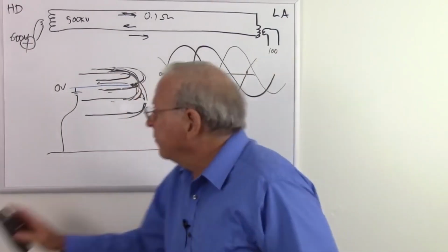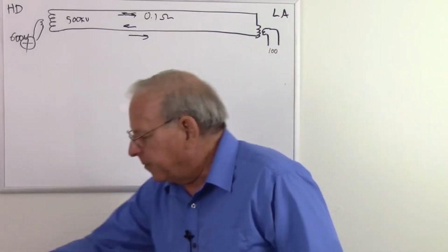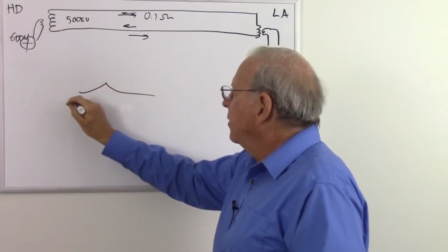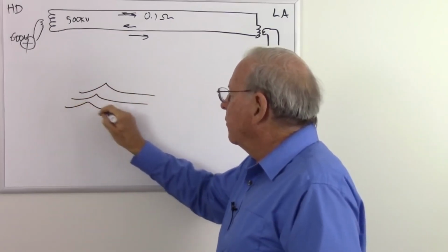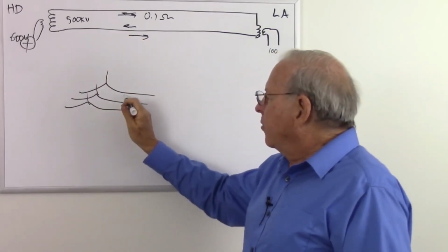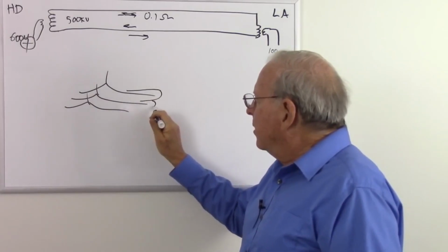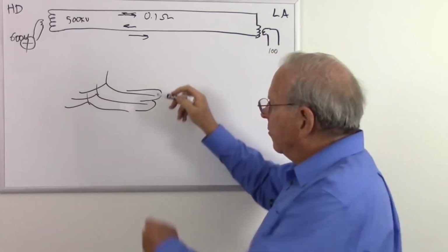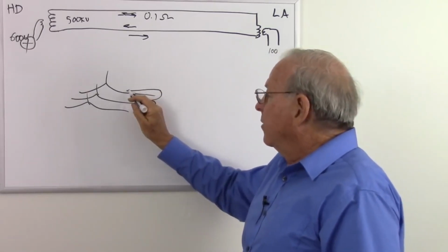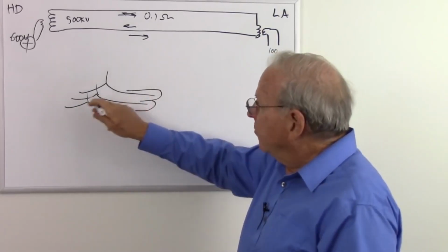So the reason we have the 3 phases, if I will declutter this and simplify it a little bit, is we have wire 1, wire 2, and wire 3 hanging from our tower. I won't draw here. And so the power is coming out this wire and returning through this one, and maybe a little through this one, just depends on the timing. They're going to be changing constantly, but they all balance out so that we don't have to have a 4th return wire. So there's our 3 phases.